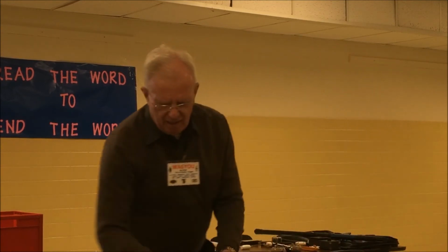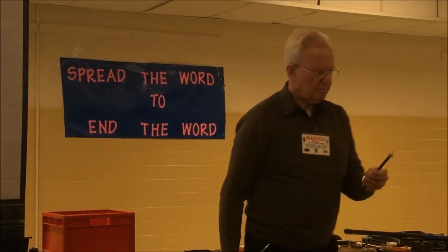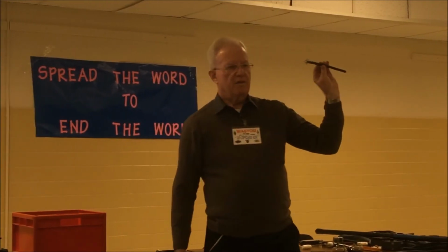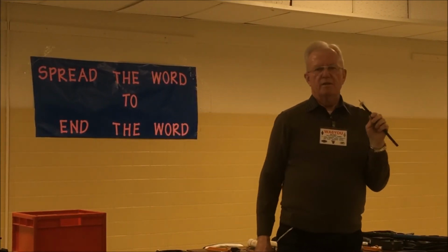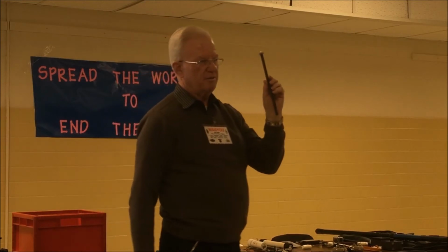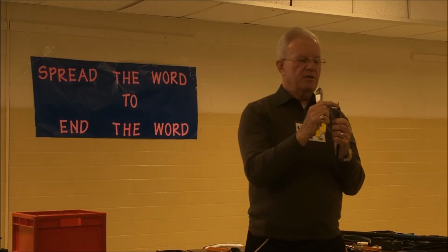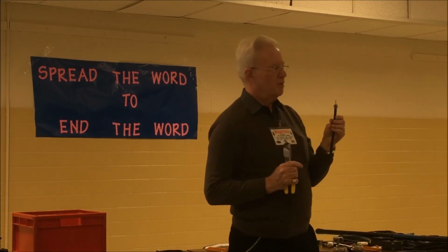Here we go. And now my favorite coax of all of them is the double shielded, either LMR 400 UF, or Belden 9913 F7. That's what I use. This is double shielded. The second shield is aluminum foil.